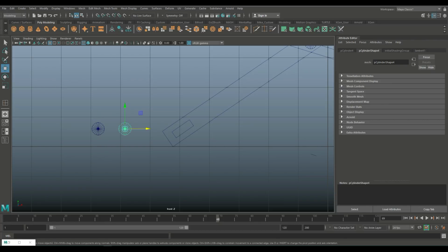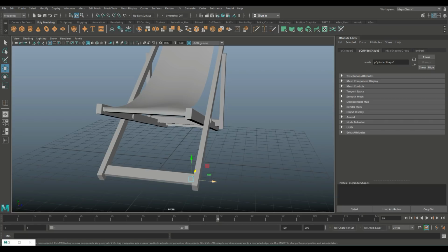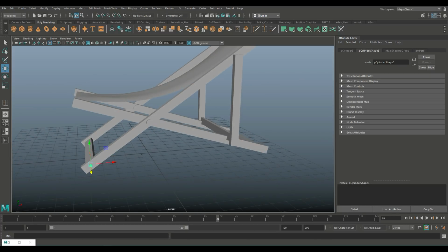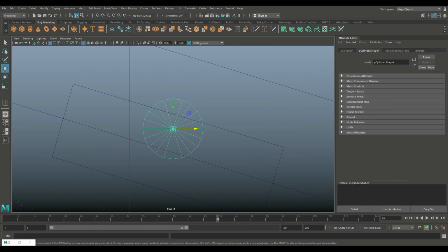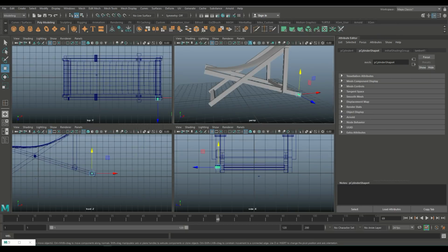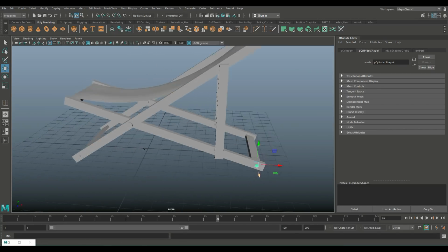We'll get rid of one. We'll take this, we'll bring it in here, we'll hit R to scale it down, like that. And then once we have all of them in place and we're happy, we can then pull them out. It's just to add a little detail, okay? So Control D to duplicate, W to move to the back. Now there we need to make sure that the position is correct. Needs to come in a bit. So there you have it.